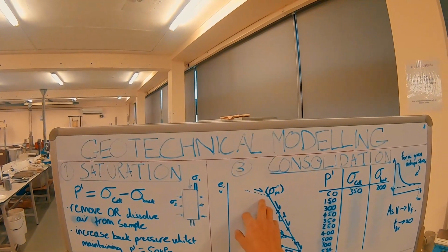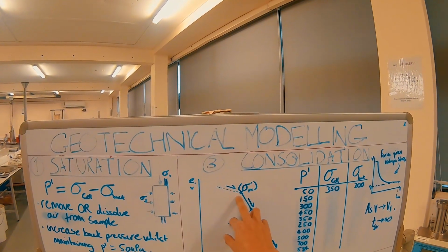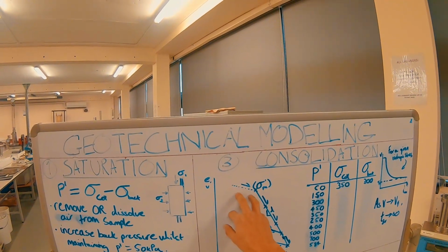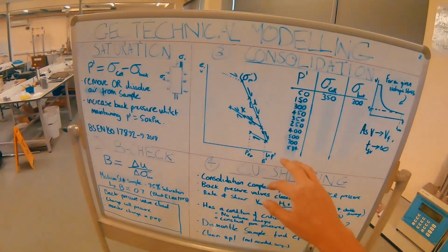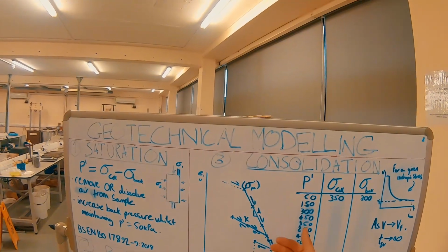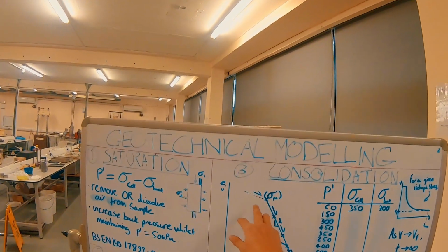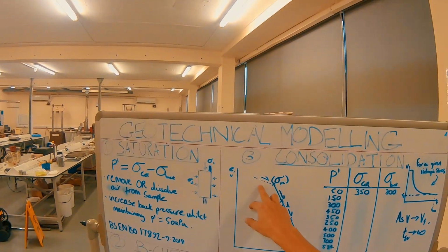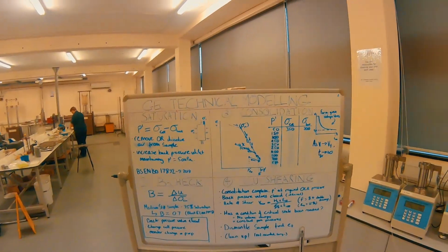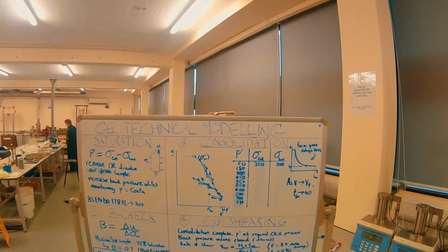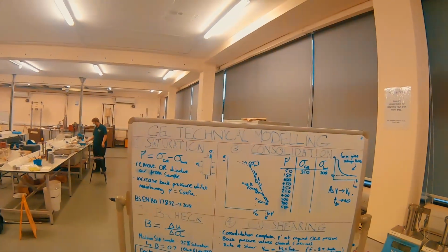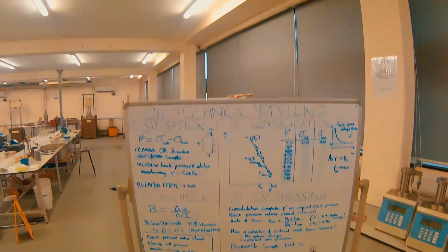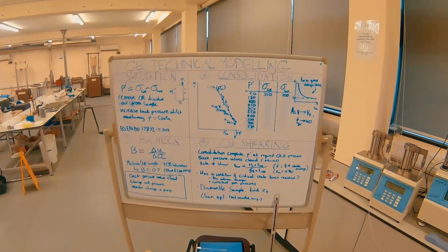Before we move to pre-consolidation stress, we are on what would be a kappa line of sorts, and we want to move past that fairly swiftly. We're not really concerned about the behaviour on this line, mainly due to the fact that the way we created the samples wasn't in isotropic compression. It was in one-dimensional consolidation, if you think back to one-dimensional compression theory.